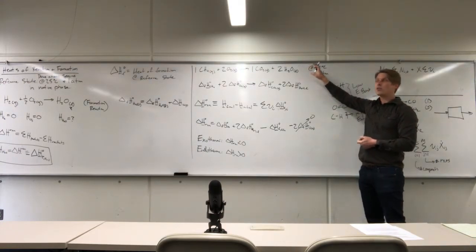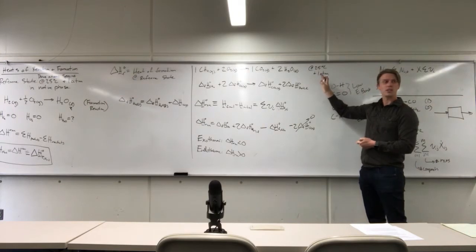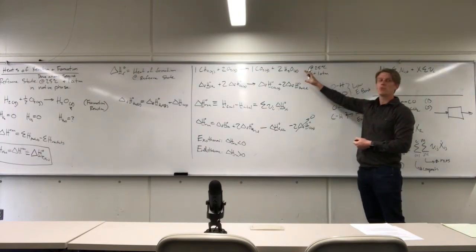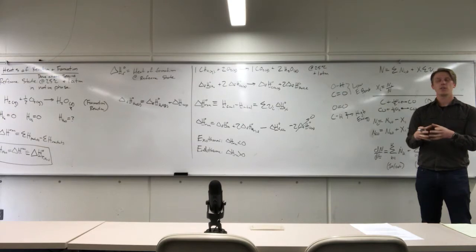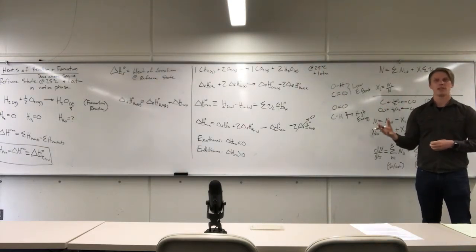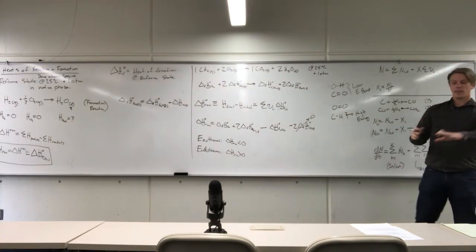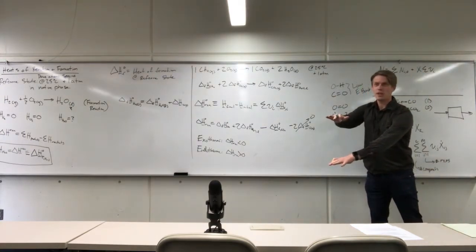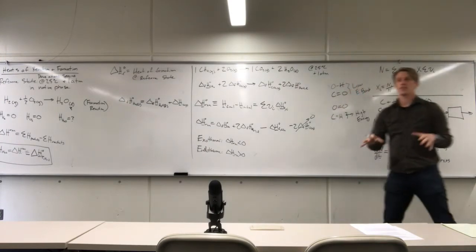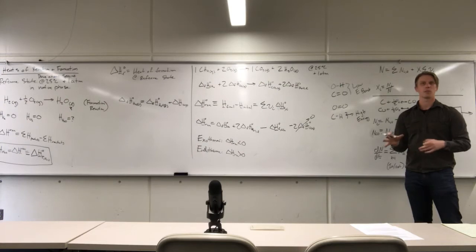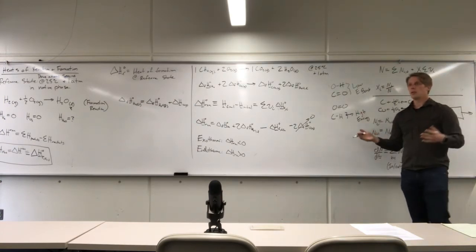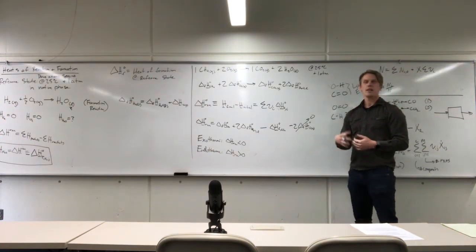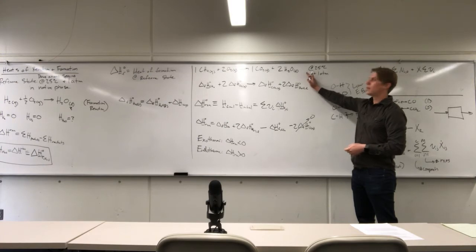And this is another reason why we don't really care a ton about gravitational energy and kinetic energy in chemical engineering. Now let's imagine how much energy goes into boiling something. That's still way more than the potential energy from gravity, still way more than kinetic energy. So let's say kinetic energy is down here. Boiling takes this much energy. Reactions are way up here. Chemical reactions consume and release way, way, way more energy than all those other processes. And that's why as chemical engineers, when we do our material balances and energy balances, we don't really care about the velocity of something going in there. I guess if you're doing really big processes with tons of fluid going through something per second, maybe it adds up over time, but in general, this is a lot of energy.